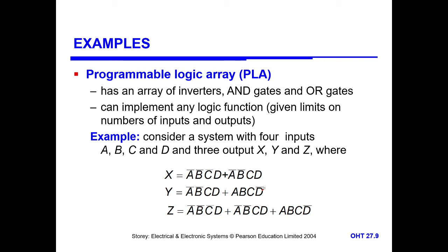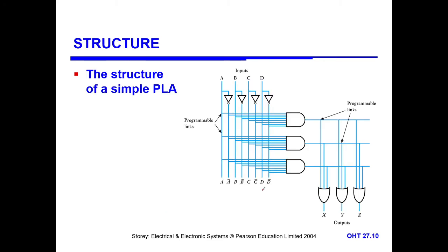It has the three primary gates such as AND gates, OR gates and NOT gates. So if we have the AND gate, OR gate, NOT gate, we can realize any other Boolean expression, so that may be sum of products or product of sums can be implemented by making use of PLA.